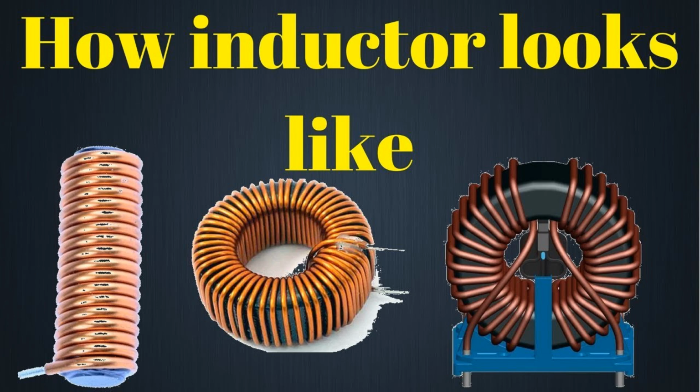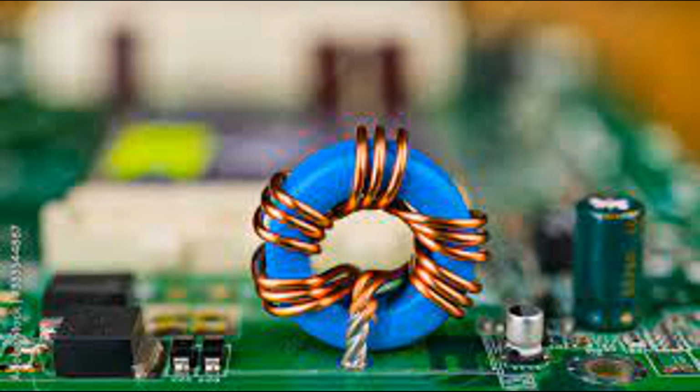Function. In transformers, inductors are used to transfer electrical energy from one circuit to another through electromagnetic induction. A transformer consists of two or more coils of wire, inductors, wound around a shared magnetic core. When an alternating current, AC, flows through the primary coil, it generates a varying magnetic field. This changing magnetic field induces a voltage in the secondary coil, transferring energy between the two circuits without direct electrical connection. Transformers are essential for stepping up or stepping down voltage levels in power transmission and distribution systems.